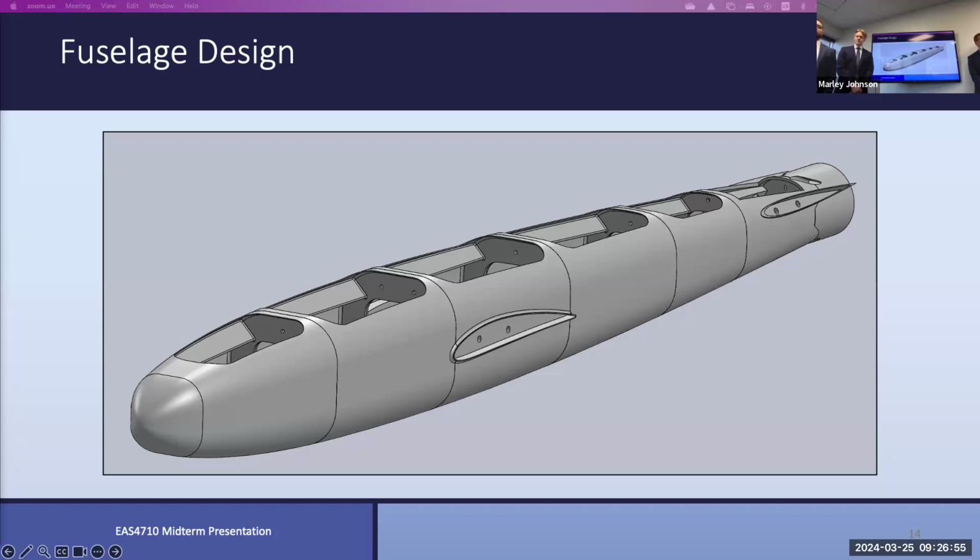Also, briefly to address your concern about lightweight PLA and also regular PLA, we are test printing our fuselage sections with regular PLA. The only reason I mentioned the problem with regular PLA being an issue with the separation for the single layer was for the wing, because we were having a lot of issues with the printers dealing with the geometry. For example, we tested one printer, and probably because of the humidity changes, it wasn't negotiating the specific curvature, but that was for the wing, with the lightweight PLA.